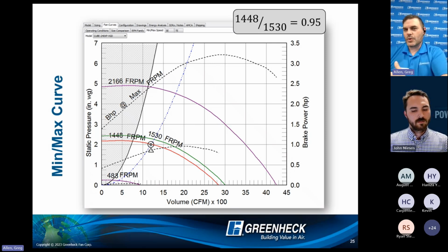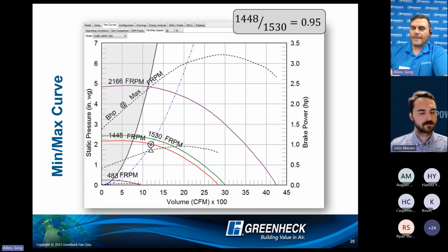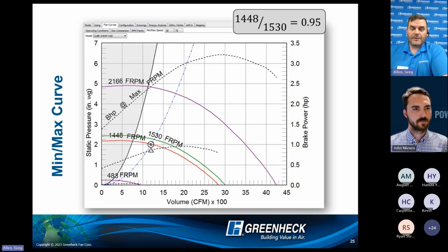There's a lot of different controls, and I guess the way I look at it, Greenheck provides a pretty good selection of fan controls, very green controls as we would call them. But because I respond to a 0 to 10 volt signal, I can use controls from anybody that outputs a 0 to 10. I mean, that's great. Mine are sized and set up for specific scenarios and tested for function and all that.